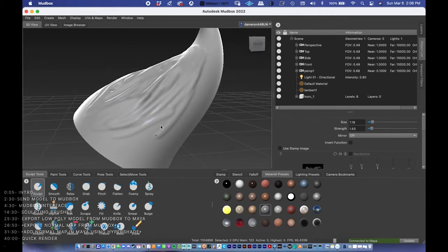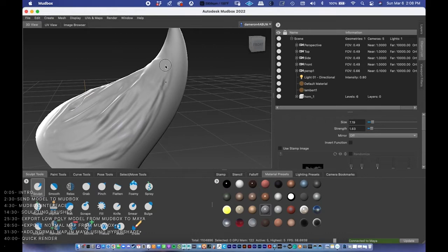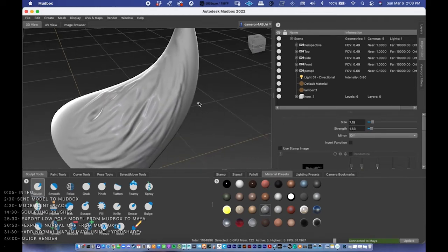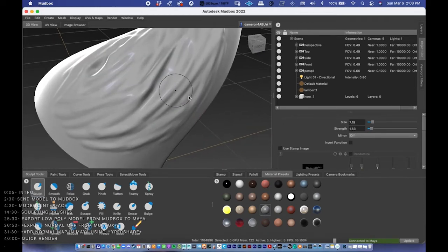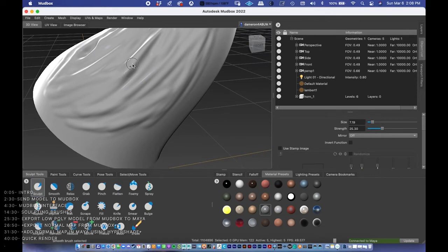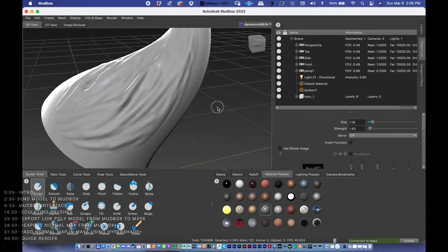And the reason that you might want to shift down to a lower subdivision level is, let's say that you want to use the smooth tool. The smooth tool is this tool right here, and you can always get it just by pressing shift. That's a shortcut. No matter what sculpting tool you're on, if you hold shift, it'll smooth. Let's do this area right here. This is a bit of a fall off, and if I press shift right now, it's doing something, but not much. I'll press edit, undo. You can see it did do something, but not a lot.